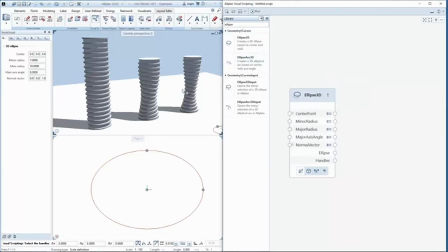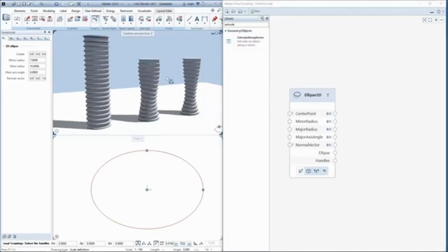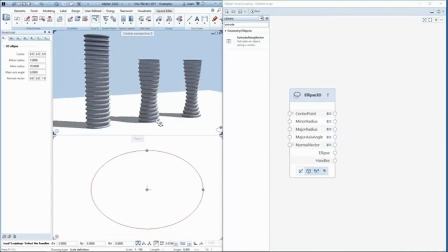There are several ways to create that. The easiest one is to use extrude, which we also have. You can just type it there. Extrude. So you can see the nodes here, but I would not recommend that, because if we see the other two examples, because we want to do all these three examples, the cross section of the glass facade at each level is different. That means if we use extrude, it's quite difficult to control the cross section at each level.